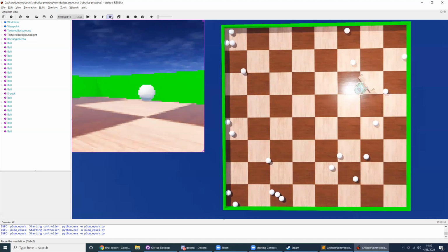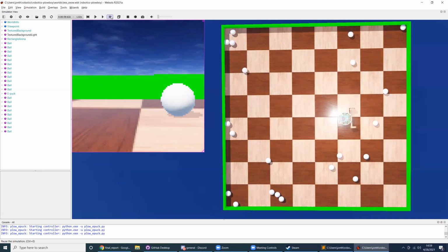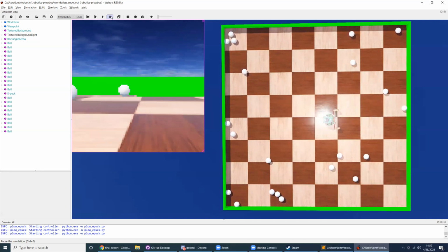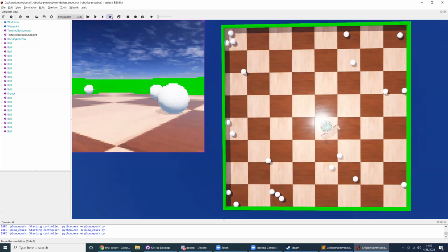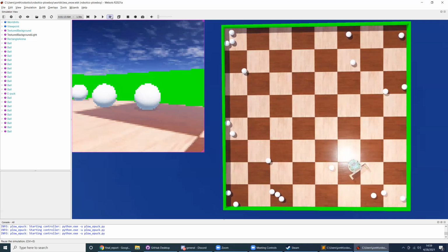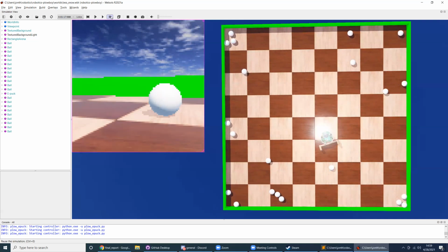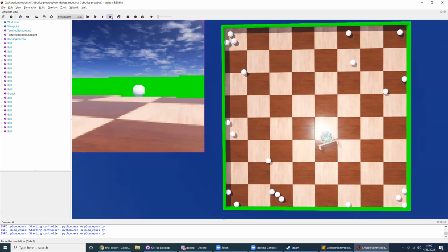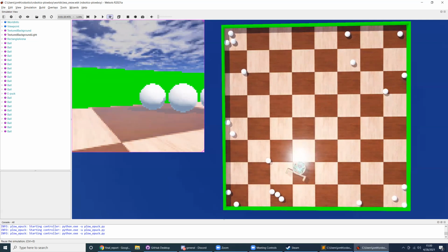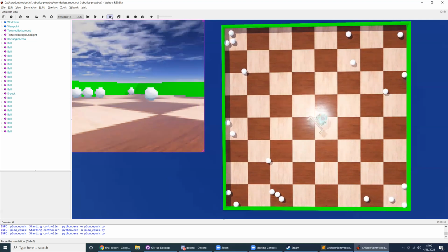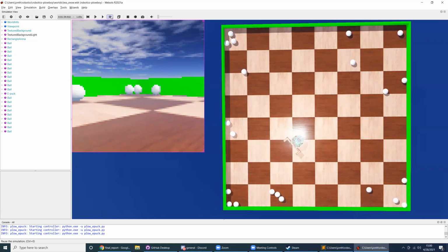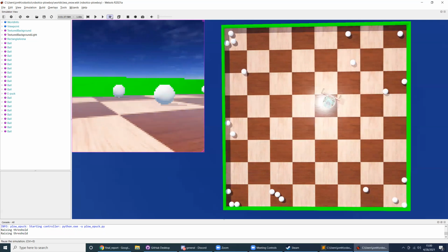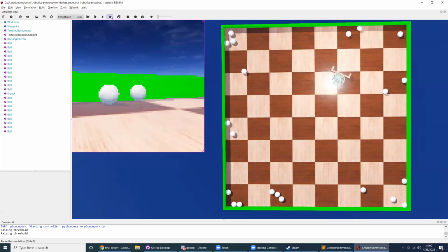So once the robot detects a certain number of white pixels in that frame, it knows, okay, this is a snow object, and it begins to plow. And then once it detects a certain number of green pixels, it knows that it's a certain distance from the boundary line, and it should begin to reverse. So it reverses for the same amount of time that it plowed for. And then the robot will spin in place until it detects snow again and repeat the process.